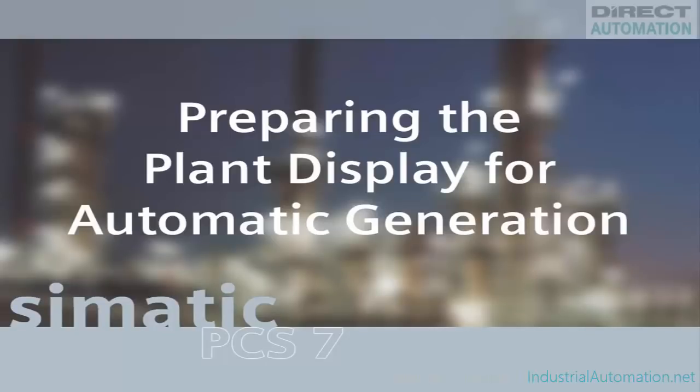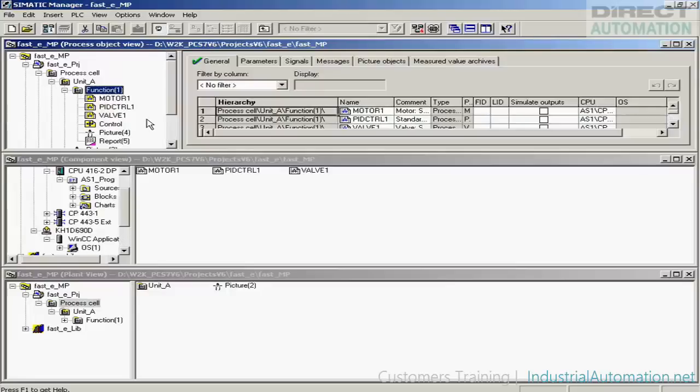These block symbols are automatically linked to their associated faceplates. Generation of these block symbols and the process for linking a symbol to a faceplate can be executed on demand. However, this function is often selected and carried out during compilation of the operator station.